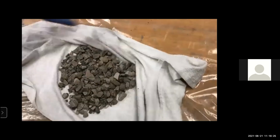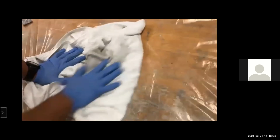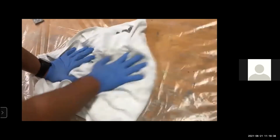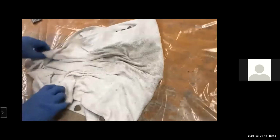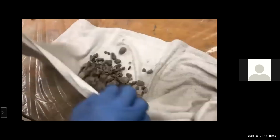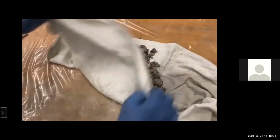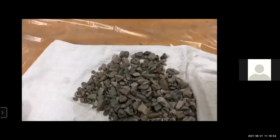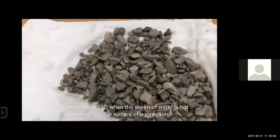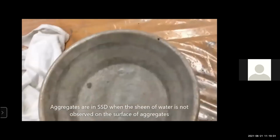So these are all our dry aggregates. Then we again try to remove all the adsorbed water which will be present on these aggregates. So basically we try not to allow any water droplets to be present on this aggregate sample. So if aggregates are in SSD condition, then the sheen of water is not absorbed on the surface of the aggregates.